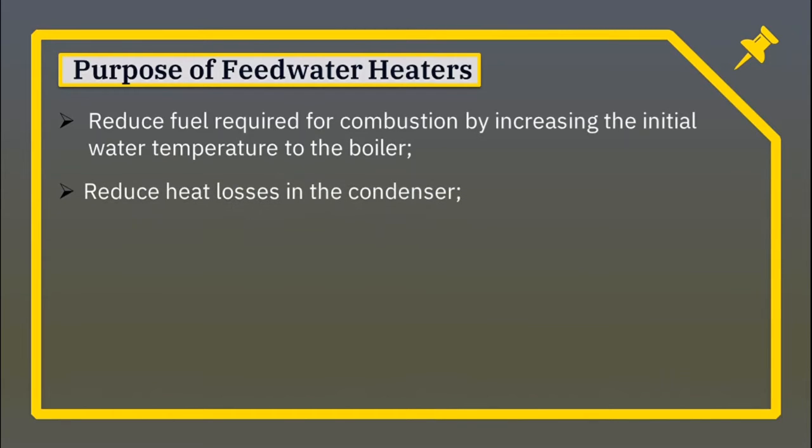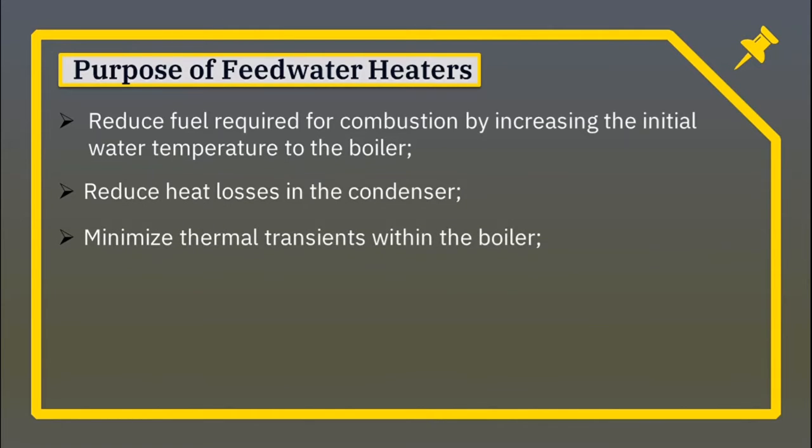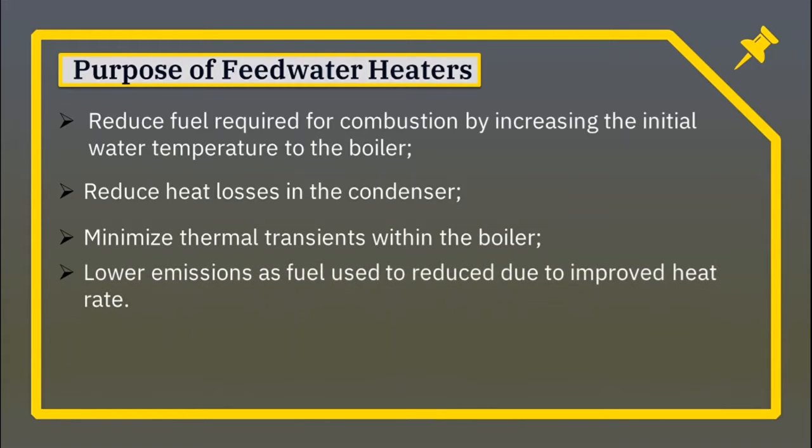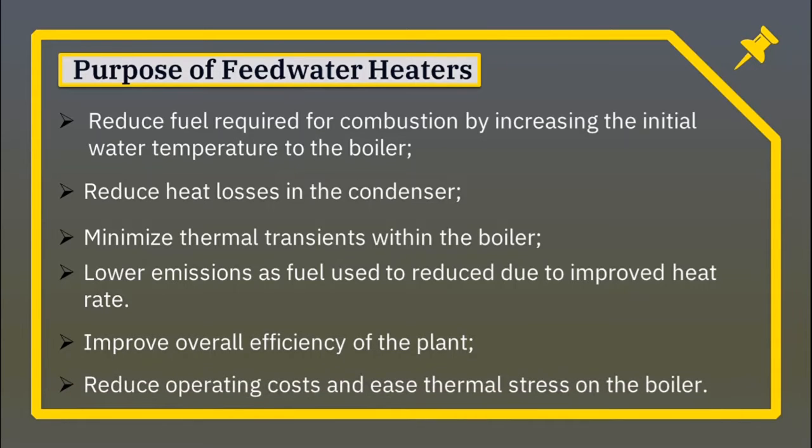Second, to reduce heat losses in the condenser. Third, to minimize thermal transients within the boiler. Fourth, to lower emissions as fuel use is reduced due to improved heat rate. Fifth, to improve overall efficiency of the plant. Sixth, to reduce operating cost and ease thermal stress on the boiler.